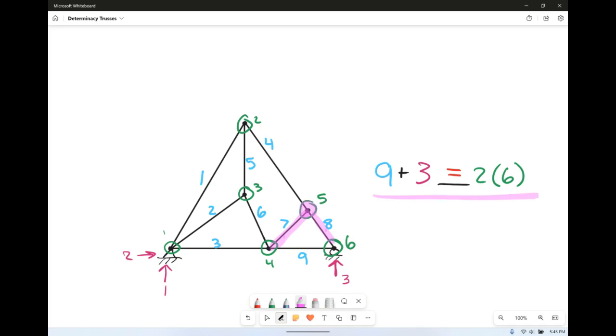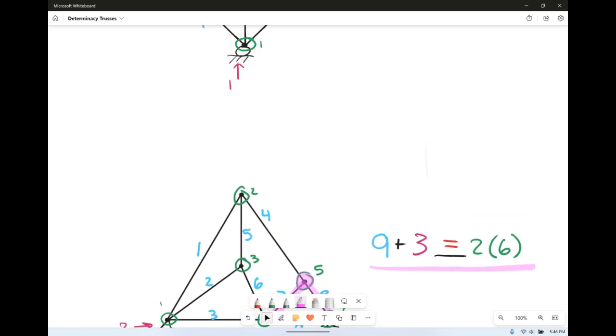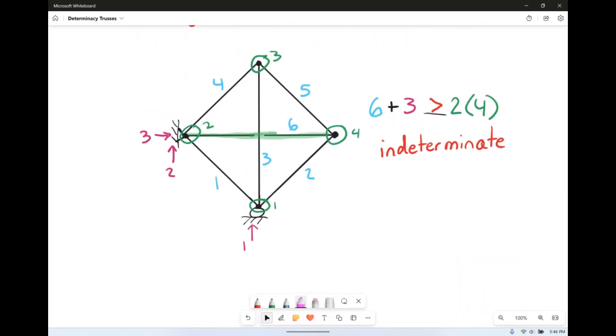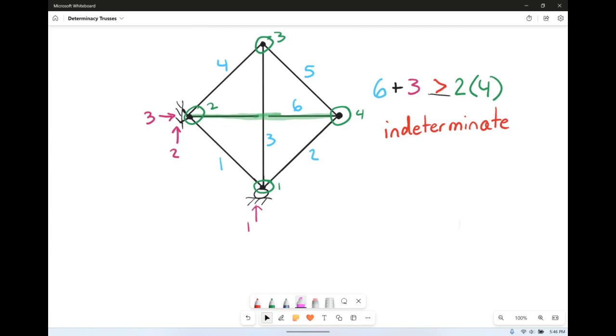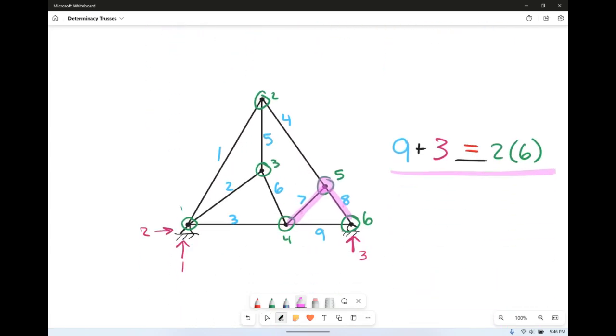So it is kind of good to note that creating indeterminate trusses, unstable trusses, if it's pretty much stable already and determinate, then you've really got to work pretty decently, not by just joining up more things. You kind of have to do the bypass method in order to get things to be a little bit indeterminate. Otherwise, you can just change it to having, say another pin instead of a roller, then it could be indeterminate. Or if you put a roller instead of a pin, it could be totally unstable. So that is just something to note with trusses.